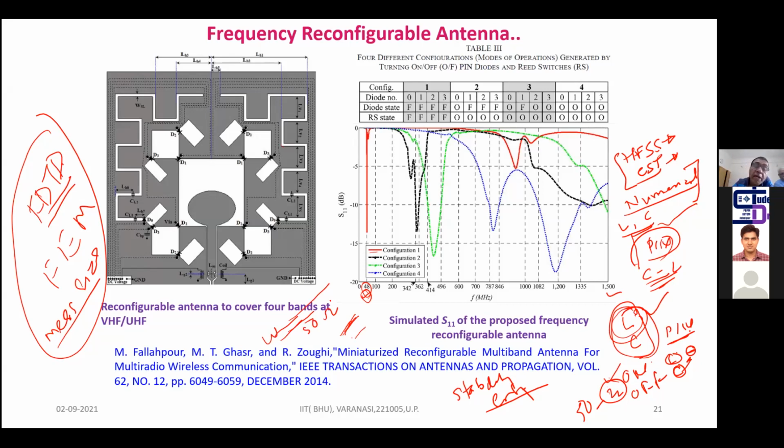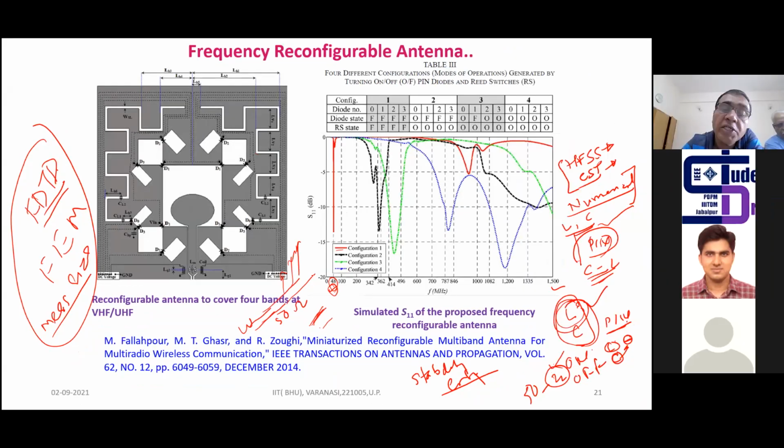But in addition to this, we get some spurious radiation. If you plot the electric field, you see some spurious radiation. We can't say the line is perfectly transmitting the signal; in addition to transmitting the signal, we get some spurious radiation. That spurious radiation affects the pattern of the patches, right? You can simulate a simple patch antenna using this microstrip line and see the spurious radiation over there. Yes, that is affected.